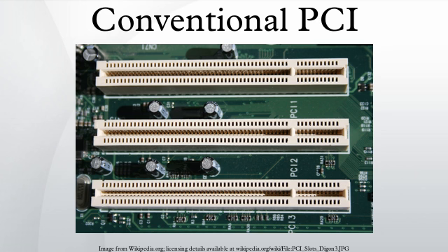PCI video cards replaced ISA and VESA cards until growing bandwidth requirements outgrew the capabilities of PCI. The preferred interface for video cards then became AGP, itself a superset of conventional PCI, before giving way to PCI Express. The first version of conventional PCI found in consumer desktop computers was a 32-bit bus using a 33 MHz bus clock and 5V signaling, although the PCI 1.0 standard provided for a 64-bit variant as well.